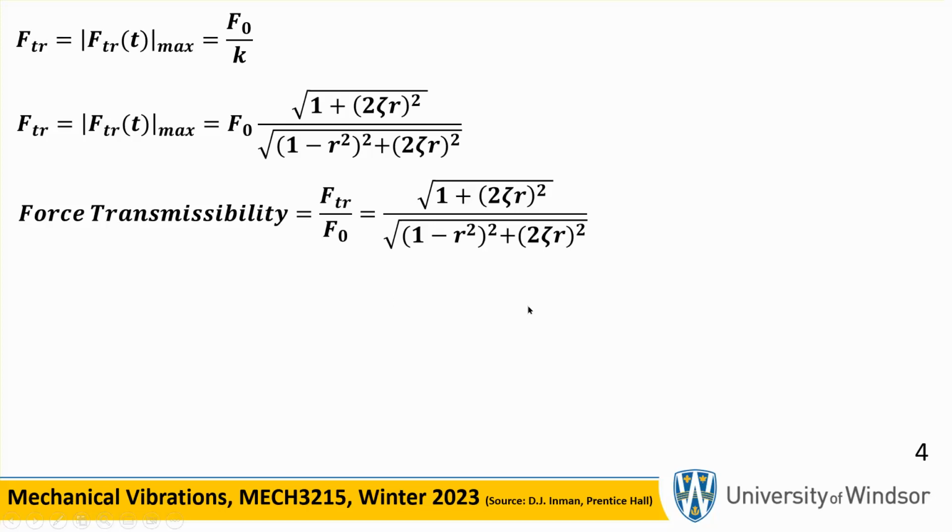The reason is that when we do the next subject, namely base excitation, we have a force transmissibility and we have a displacement transmissibility. So I would like, as much as possible, to keep them distinct. But right now, never mind the displacement transmissibility; it doesn't apply to the present case. It's just force transmissibility that comes into the picture.